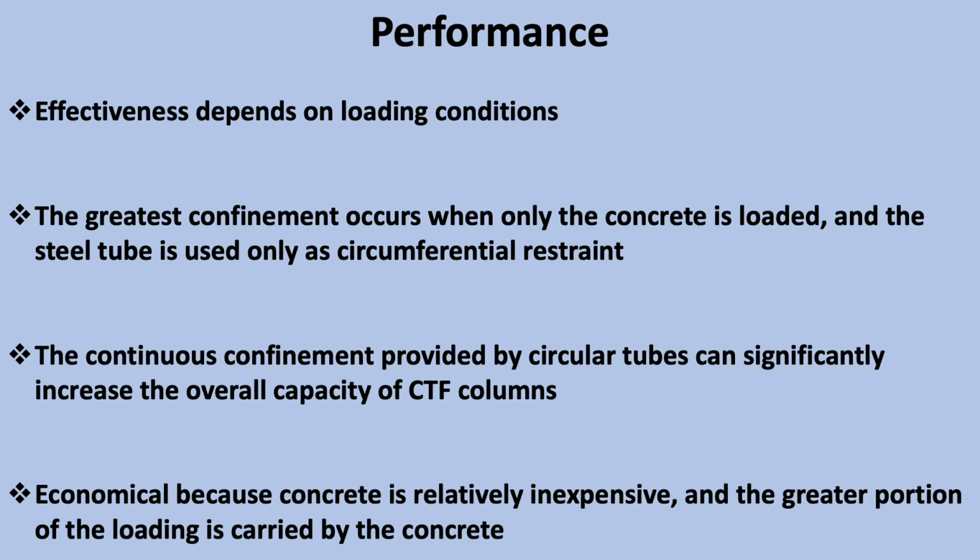The continuous confinement provided by circular tubes can significantly increase the overall capacity of CFT columns. Circular CFT columns can also be very economical because concrete is relatively inexpensive and the greater portion of the load is carried by the concrete.